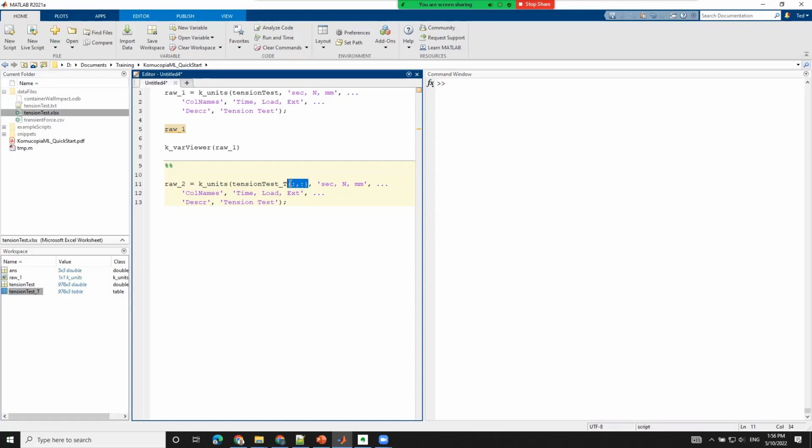So this syntax in MATLAB for a variable that's of type table tells it: give me all the data, all the rows and all the columns, all the data inside the table, give it to me as data. So give me the guts. So that's going to be basically just a numeric array.